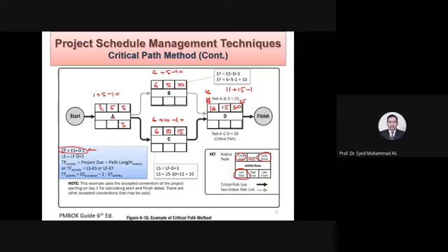Okay. Now you see you have the formula. Late start is equal to late finish minus duration plus 1. So late finish is 5 minus 5 days, your duration, plus 1. So you get what date? What is the result over here? 1, sir. 1. Okay, logical. This is also logic.